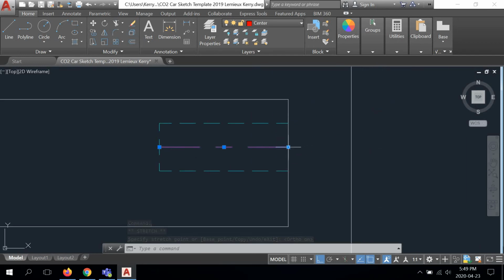And now the center line needs to extend a little bit from the front and the back. This is something that you were taught in the AutoCAD unit. Anything that represents anything circular or symmetry requires a center line. We were extending center lines 6 millimeters in our metric drawings.